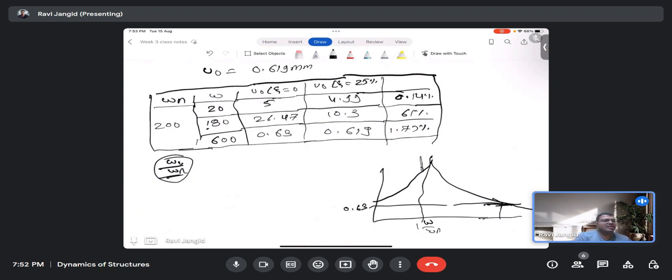So in this question we can see, when my system is near the maximum, omega by omega n not exactly 1 but around 0.9, my reduction in the response due to damping is 61%. So if my omega is equal to omega n, my damping controls my response. Do you agree with that? If my omega is in the resonating condition, damping controls my response. Do you agree?